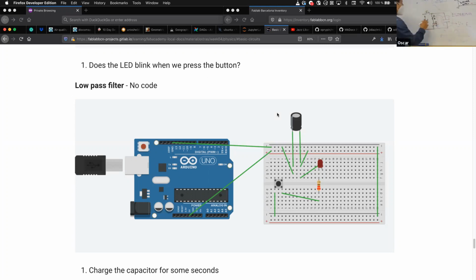You won't see much. When you open the switch, the power disappears, and the capacitor is charged and connected to the LED. So it will discharge through the LED. Even if you don't see it visually, it discharges through the LED and makes this nice fade out of brightness until it's totally discharged.